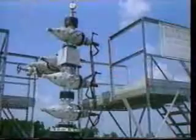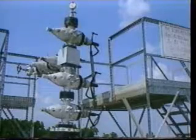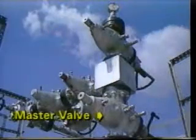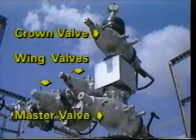As we said earlier, the tubing head marks the transition from the wellhead assembly to the flow control assembly. The flow control equipment must be able to shut the well in, control its flow rate, redirect flow from a vertical to a horizontal path, and allow injection as well as production through the equipment. The most prominent pieces of equipment in the Christmas tree are gate valves, located directly above the tubing head adapter. These include the master valve, crown valve, and wing valves.